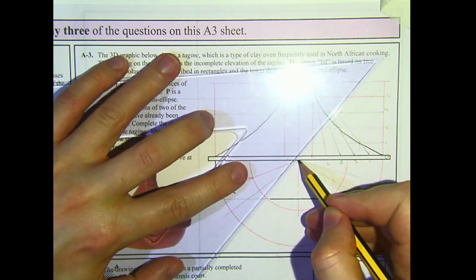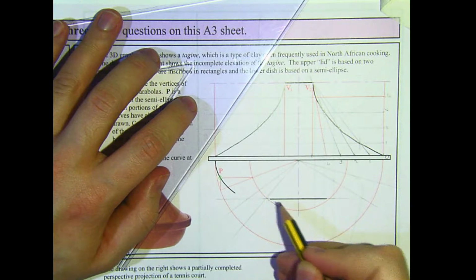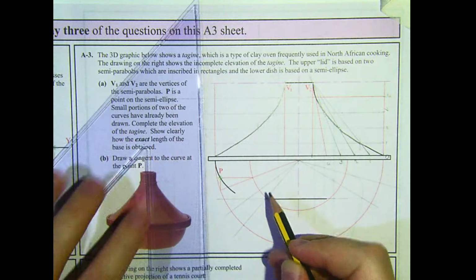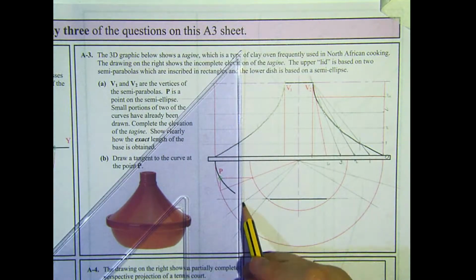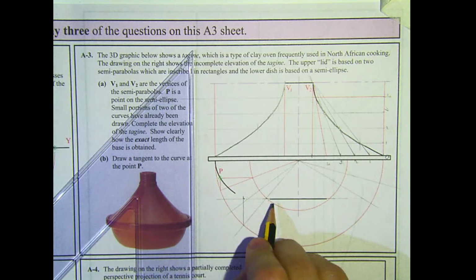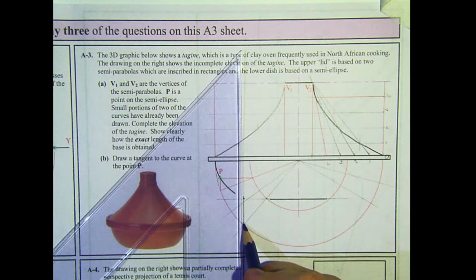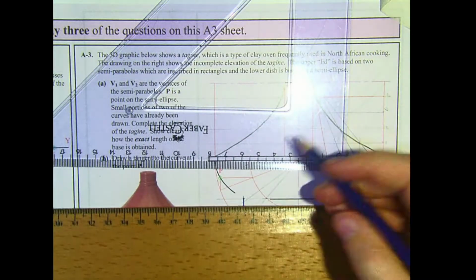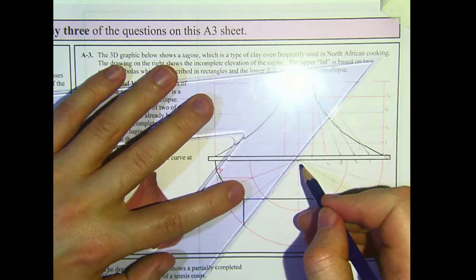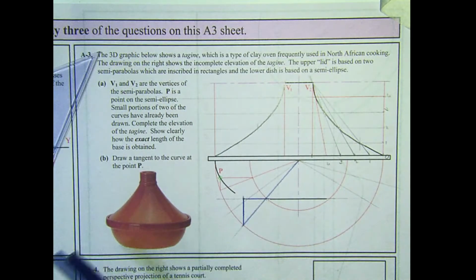So doing that is from the center through where this point is here. So we've extended this horizontal line until it touches the minor auxiliary circle. Then I'm going to go perpendicular to the major axis, so that's going to give me this point. At this point here, that's the exact point from where it transitions from the ellipse to the base. Okay, I'll just change the color of that. So we've extended that on just a little bit more, and we've got this line coming from the center through this point here. So that gives us that exact point.